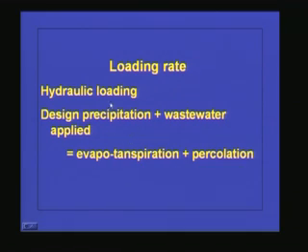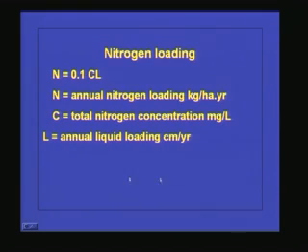If you add more water, then what will happen? Water logging will take place. And this is the nitrogen loading, because nitrogen loading will be based upon the nitrogen uptake capacity of the plants. So N equals 0.1 times C times L, where N is the annual nitrogen loading in kilograms per hectare per year, C is the total nitrogen concentration in the effluent, given in milligrams per liter, and L is the annual liquid loading in centimeters per year.